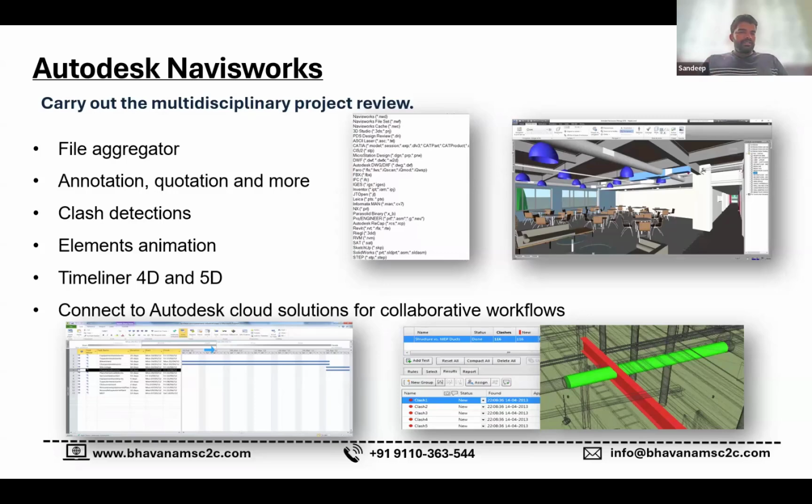In this coordination, it will identify the clashes between the discipline models, such as structure, MEP, and so on, so that we can simulate the construction process easily. I'll show you in the next slide what simulation means. Generally, this simulation supports the 4D model, or the timeline model. We have length, breadth, and height information, which is 3D. If you add time to this model, that is called 4D. 4D means the fourth dimension is time.